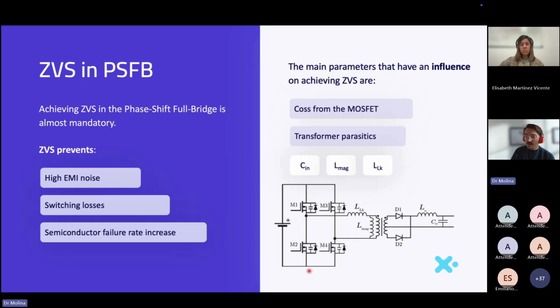So here in the primary side, we have this full bridge where we have 4 switches. And in the secondary, we have 2, could be switches or diodes. In this case, it's diodes, but you also have losses here. And the losses that you have in a switch are 2 types of losses. One of the losses are due to the conduction.